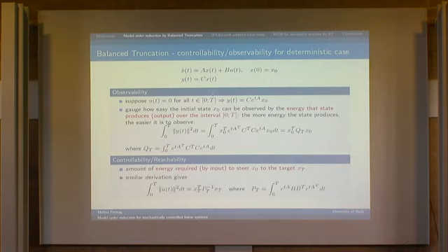And you can write this in the same way. So what input u do you need? What's the energy u that you need to steer an x naught to a target x of t? So it's only concerned with the first equation, the state equation. So you can compute this u, the energy. I left out some of the computation here, but it turns out this is another inner product that you get, and P is a similar matrix to this Q matrix, another positive semi-definite matrix.